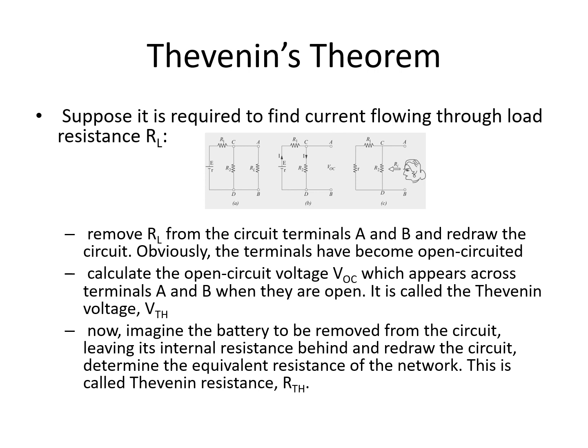Suppose it is required to find the current flowing through the load resistance RL. So what are we going to do? This is our load resistance RL. You can actually solve this type of problem using the previous techniques that we have already discussed: Kirchhoff's laws, mesh analysis, and nodal analysis. And this is the approach when we make use of Thevenin's theorem.